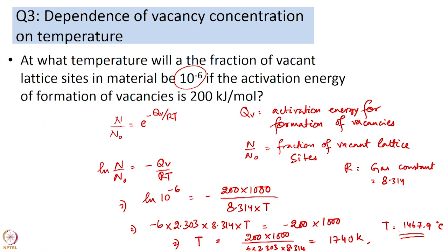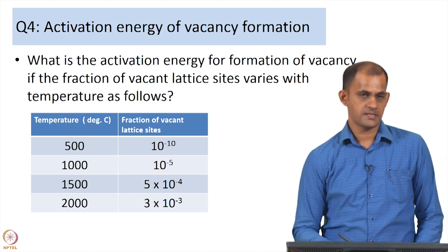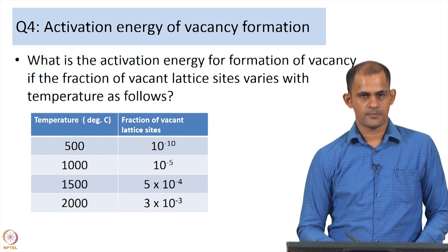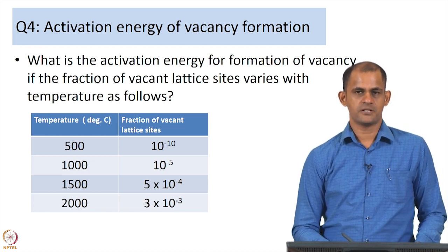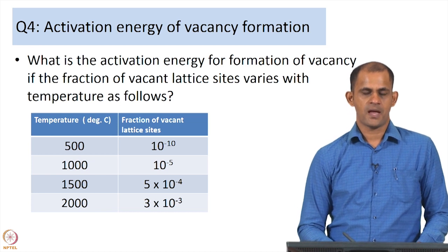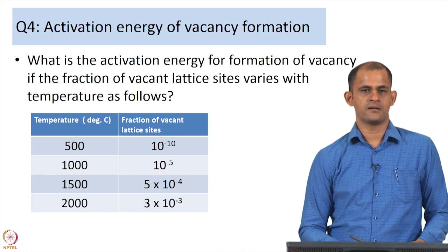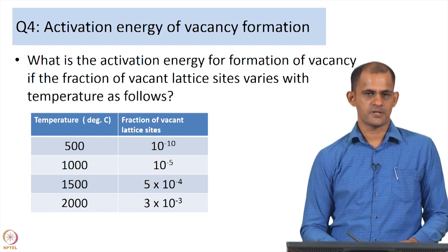Now, let us look at a slightly different version of the same problem. In this problem, which is a variation of the earlier problem, I am asking you to determine the activation energy for formation of vacancies, and what I have given you is different temperatures and the fraction of vacant lattice sites corresponding to these different temperatures.